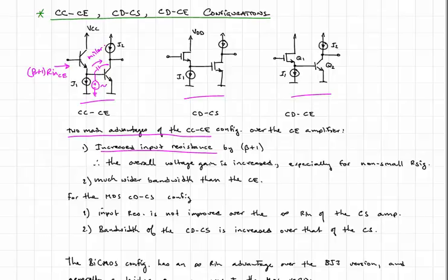But the problem is that with the standard common emitter amplifier, there is a source resistance, R_sig, and when current is demanded of it through this Miller capacitance, that causes voltage to drop at the base. And so what we need is a lower impedance source to drive the base of our common emitter stage, and that's precisely what the common collector stage does. It lowers the resistance.